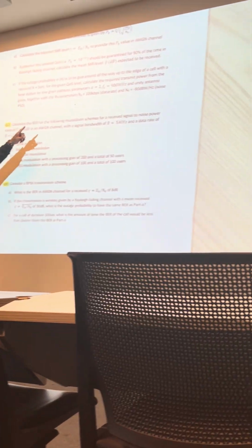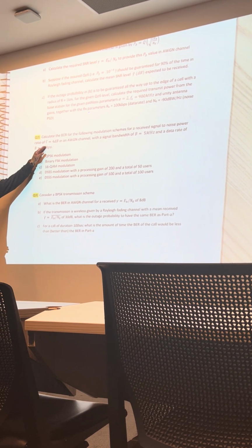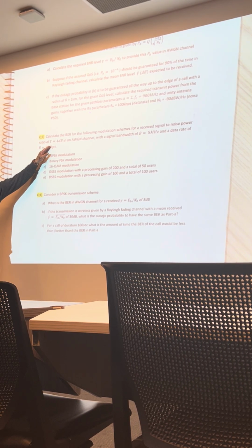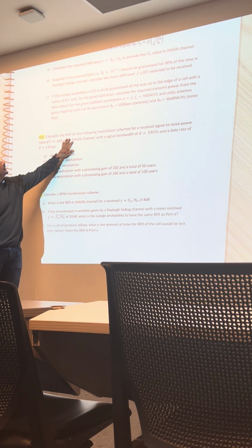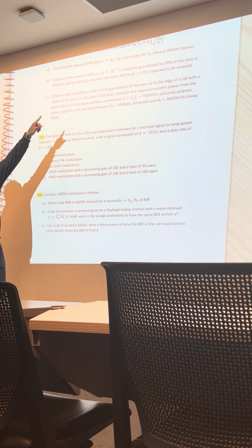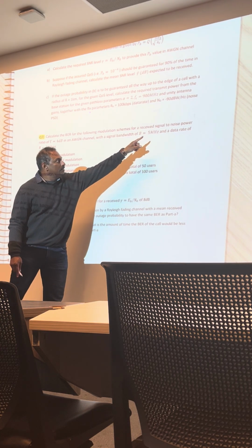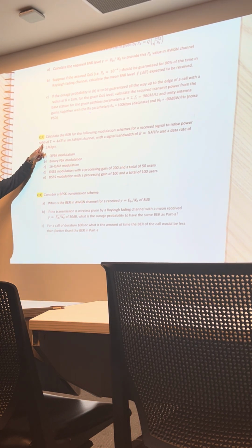megahertz. The other signal to noise ratio that we refer to is the Eb/N0 or Es/N0, bit energy to noise spectral density ratio or signal energy to noise spectral density ratio. That will be clearly defined. So in the previous question, in part A, we define SNR as Eb/N0, so it was clearly mentioned what SNR we are referring to. In this problem, it's the signal to noise power ratio, so that's Ps/Pn, all right?